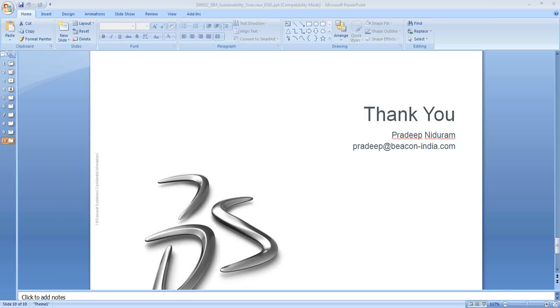I have one question here. Let me read out the question so that you all know what it is. Transportation from Asia to USA would increase the carbon footprint, but how does it work when cost is considered, where manufacturing cost is less in Asia when compared to USA? Right now, using SolidWorks Sustainability, you can specify the regions of manufacture and regions of usage. Like in the example we did Asia to USA, and then we changed it to USA and USA. Doing that, you can see how the environmental impact is affected.